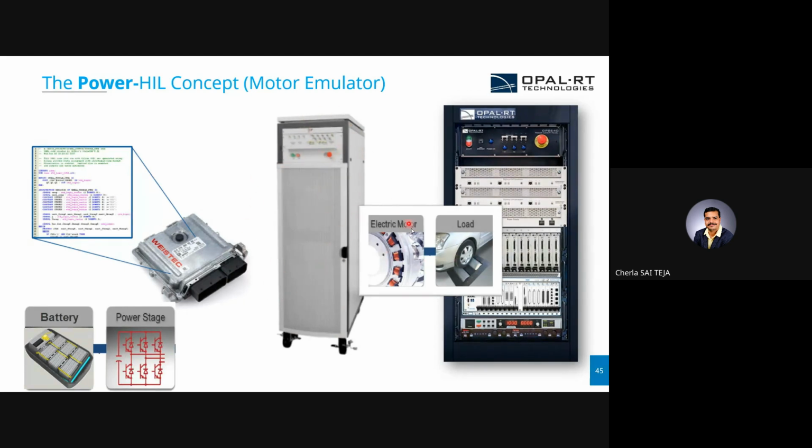Whatever motor characteristics we want, we'll first simulate them on the real-time system, take out those motor characteristics, and feed them to this motor emulator. These emulators are rated in a few kilowatts, starting from 60 kilowatt. It can go up to a 500 kilowatt motor, and the output of this power-level motor emulator will be connected to this traction inverter.